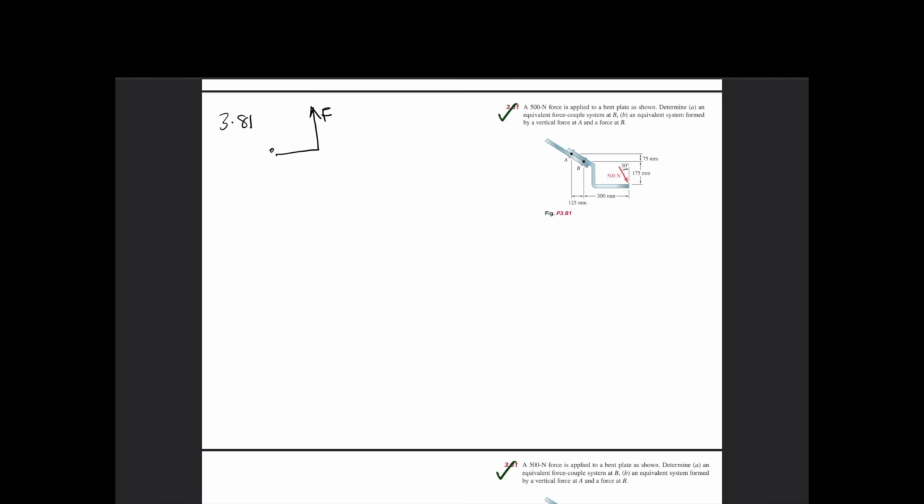a force acting here, and the distance r, we are told from our previous classes, through the principle of transmissibility, that a force can be made to act at any point along a straight line and have the same effect. But if we want to move this force to another point, let's say to this point O, to this origin here, we cannot move it arbitrarily, right?